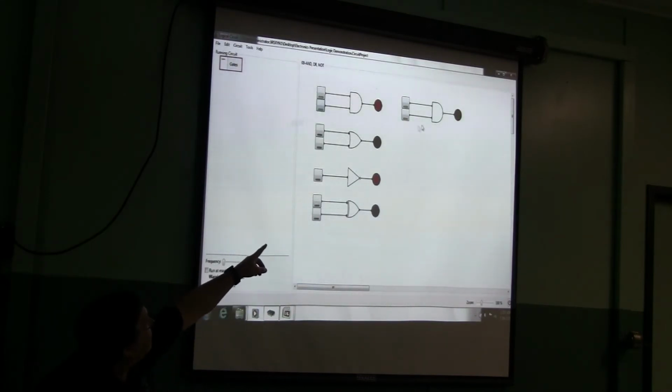So the AND gate and the NAND gate, there's a little bubble there. It's hard to see on this simulator, but it's a little inverted output. These gates function exactly the same, except that the output is backwards. The OR gate, if either of the inputs is on, the output's on, or if both of the inputs are on, the output's on. Here's our exclusive OR. If one is on, the output's on. If the other is on, the output's on. But if both of them are on, the output is off. The inverter, just on is off is on. Okay?